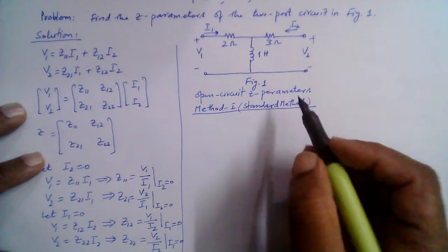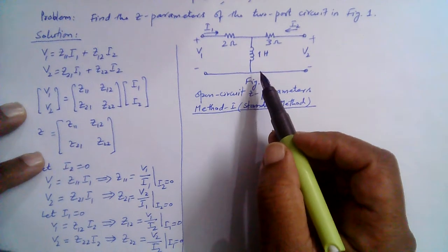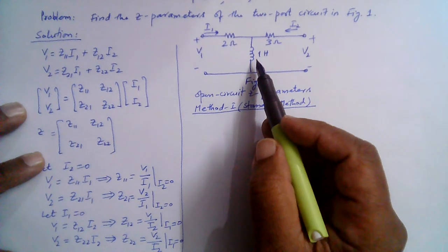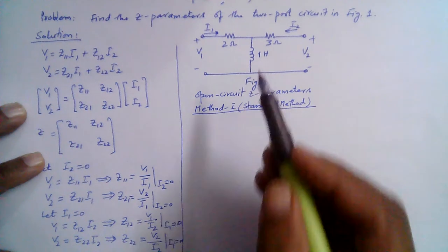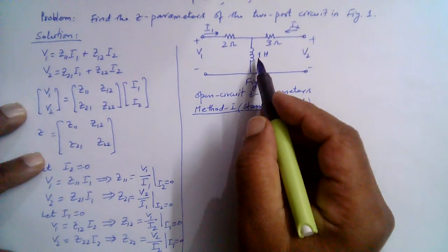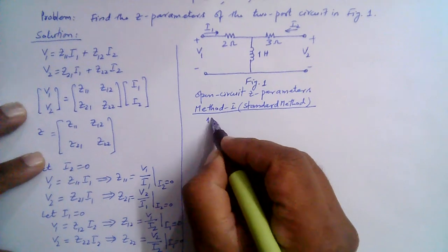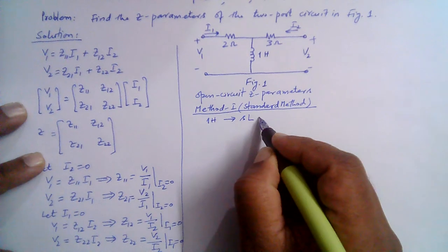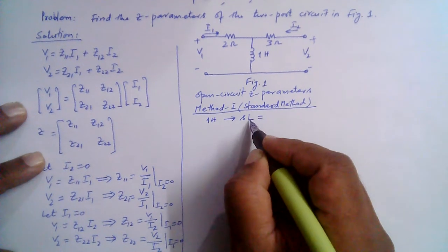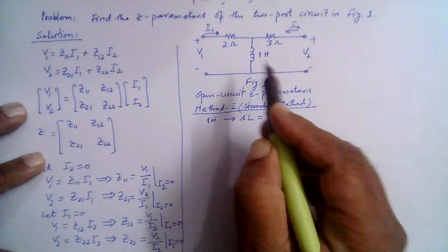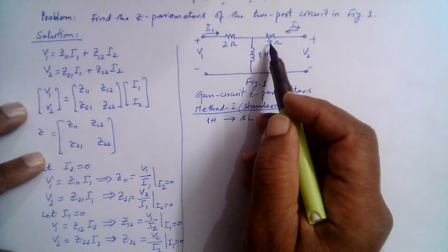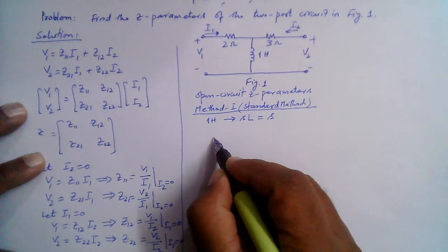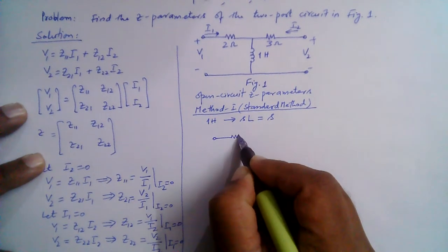So when we are given a circuit, if there are any time sensitive components like the inductor here, we must first transform it into the frequency domain using the Laplace transform. So for this 1 Henry inductor, this will be SL in the Laplace domain, frequency domain. So L is 1 here, so that is S, right? The resistors are insensitive to frequency, so they remain the same in the frequency domain. So we transform this circuit to the frequency domain first.